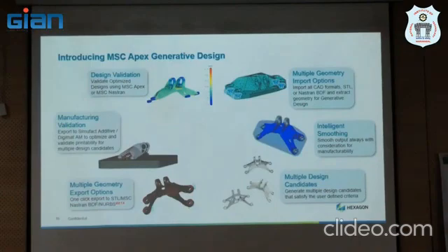If you look closely, this is a support structure. If there is an internal cooling channel and I generate a support, how do we remove it after printing? So there will be challenges from the manufacturing point of view as well. That can be taken care of by, as we always say, first running a thermomechanical simulation to understand the manufacturing feasibility, then we can go for a final design validation.